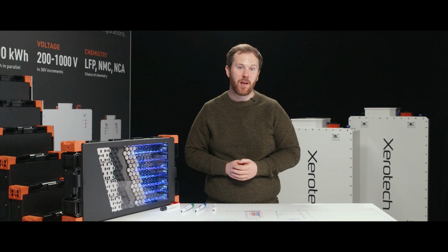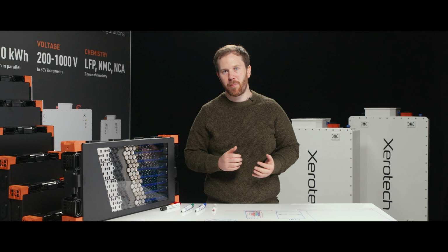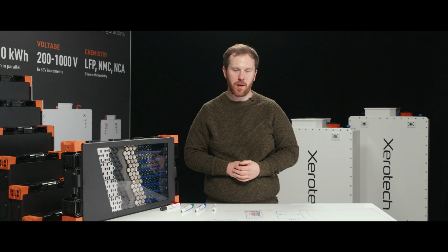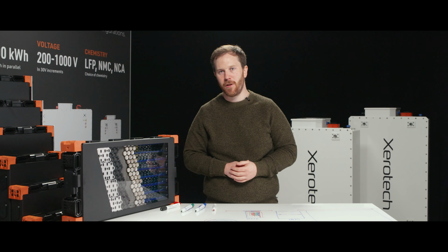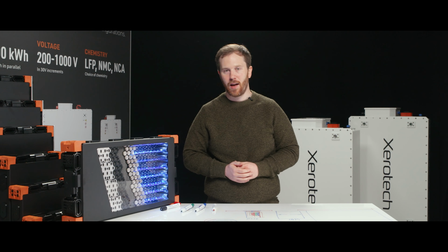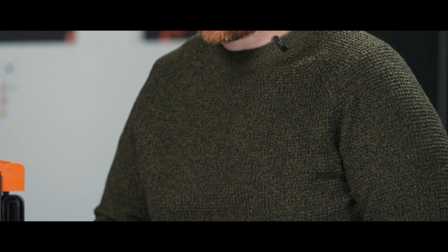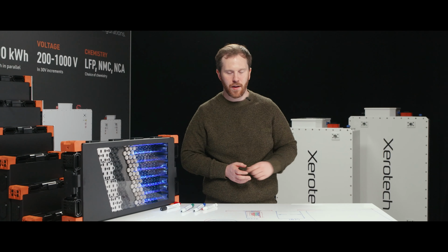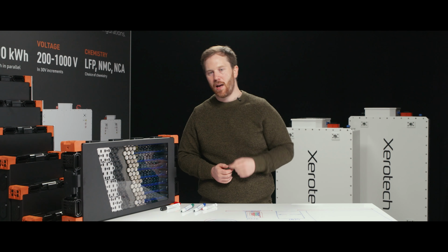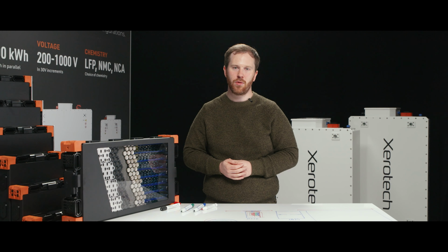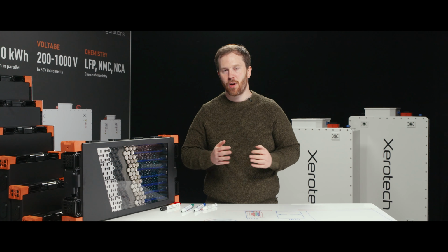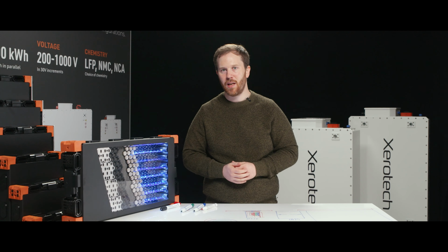Thermal management is incredibly important for a lot of future applications, especially hybrids, which are going to be a big thing for heavy duty industrial vehicles that are going diesel electric, as well as full BEV, and also high performance vehicles that generate a lot of heat. You must have strong thermal management for these, or it can result in a safety risk, because if you keep discharging on these cells, their temperature will just keep climbing. And if it reaches a certain threshold for some chemistries, they can go on fire. So thermal management is very important to maintain the safety of the battery.